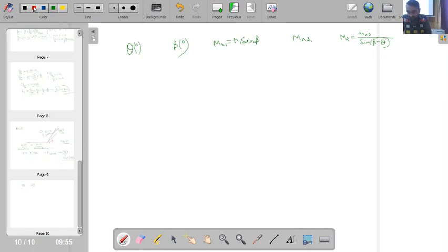So first I have guessed the value of 20 degrees. This is my initial guess. Corresponding to 20 degrees I have got beta as 39.4 degrees, Mn1 was 1.777, Mn2 was 0.621, and M2 was 1.87. So it means corresponding to deflection of 20 degrees I am getting the higher value of M2.